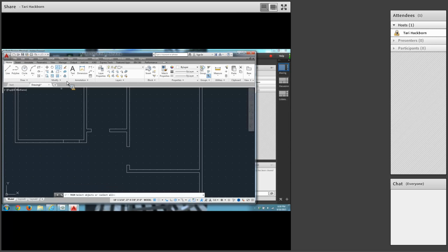All right, let's make some doors. The doors are all at 45 degrees. Polar is already turned on down here in the status bar. You can right-click on it or select the little triangle here, and make sure you click right here so that it shows you every 45 degrees. Because the default was set to 90. So click here, you'll see every 45 degrees.